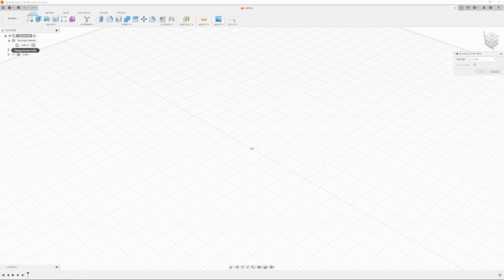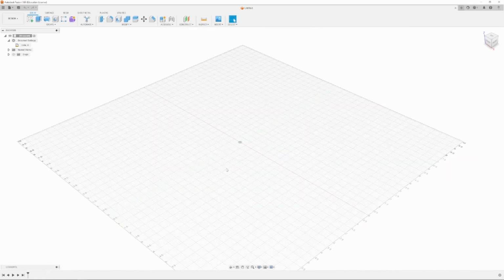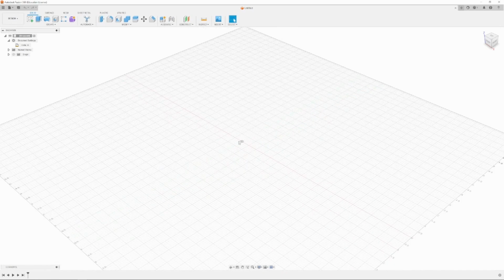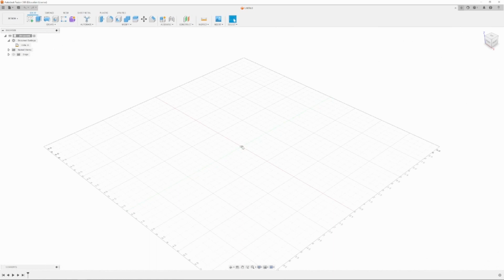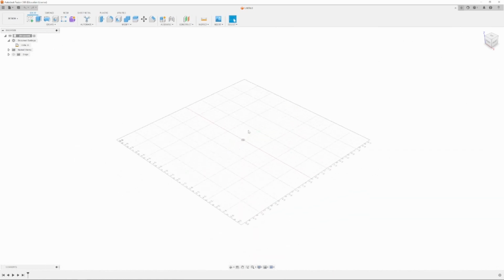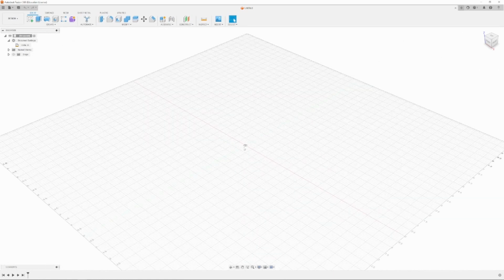So if you click on the little edit thing with the pencil here, you can select unit type, inches, and then you'll check mark the box that says set as default. And when you hit OK, it will keep that for every project in the future for you. Since in America we mostly work in inches, even though it's a lot harder than working with millimeters and metric, it's kind of nice just to be all on the same page, so that everything is defaulting to inches.